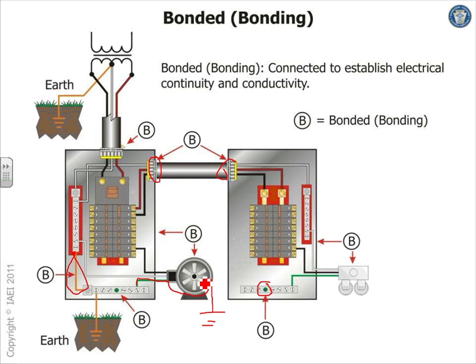For many years, you had to have your lightning grounds separated a few feet from equipment grounds, because lightning could kick back into your system. It was a big change, because they tried to keep those distances for lightning rods, and now they're all bonded together. Right now, the code requires you to bond every grounding electrode system, including the lightning.